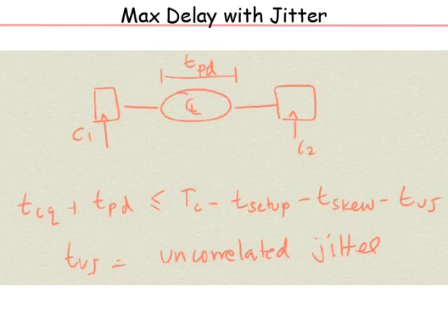odd number of stages, you loop it back. So the period of that ring oscillator is determined by the propagation delay, and propagation delay is determined by the current and the load capacitance. Capacitance is something fixed that you calculate, and it doesn't change with time. But the currents can change every time there is a charging or discharging event.